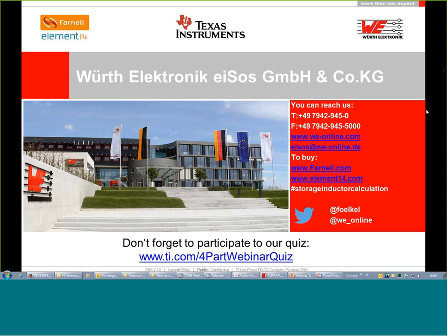Well, when you are making a buck converter, you have a source, which could be a battery, and you take this current not continuously. Every time the current is coming, you disconnect and connect. You take this current and charge the inductor. That means you will automatically generate a wave on the input because you're not taking the current continuously. This is the buck.